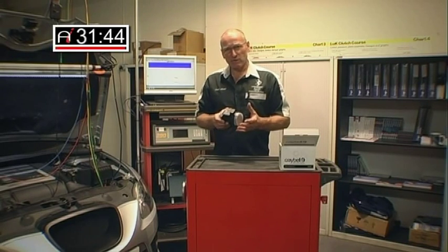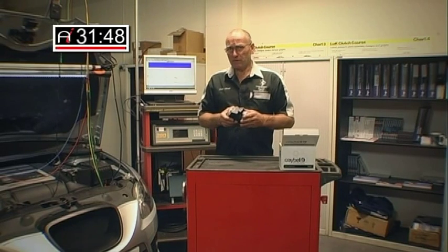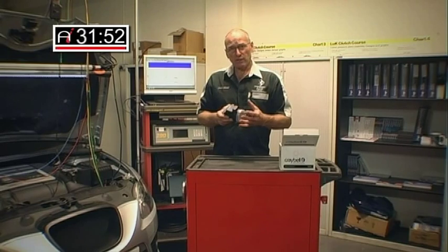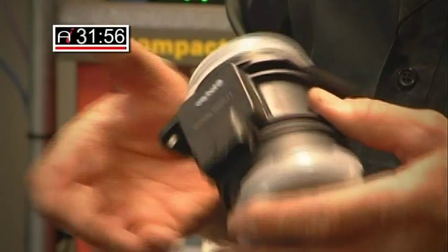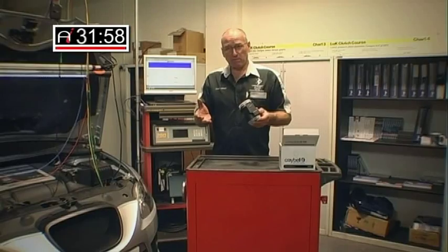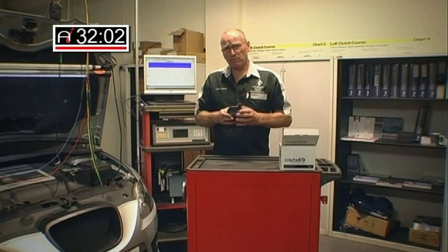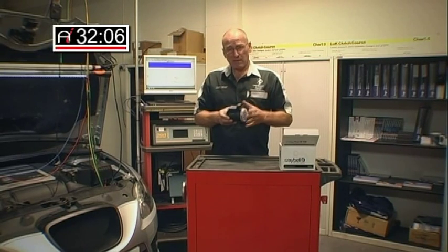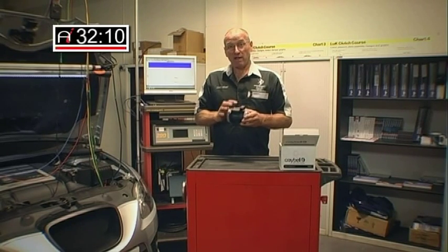Diesel intake systems really do get very, very badly contaminated, and we're now looking quite thoroughly into processes to recover the condition of the engine without major mechanical dismantling and work which involves replacement of very expensive parts. EGR valves, air intake systems, quite expensive replacement parts. So we're now looking to other methods of recovering those. So don't blame the failure of an air mass meter purely on its own devices. These, left alone in the right environment, often are very, very reliable.